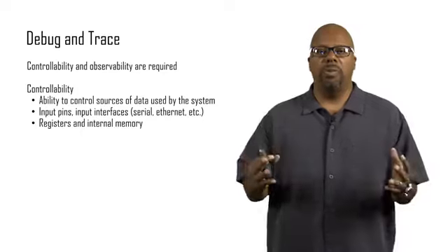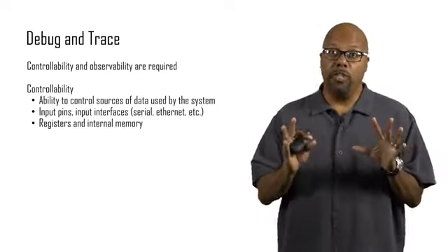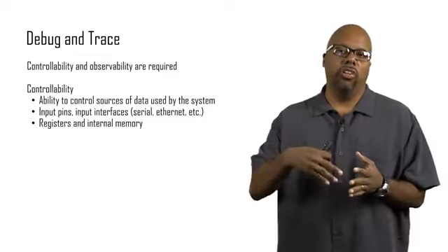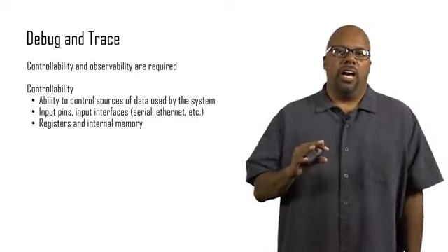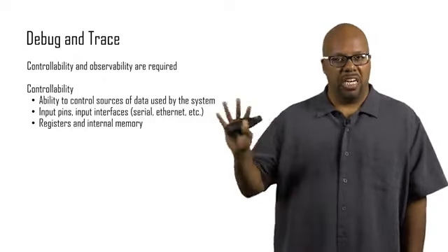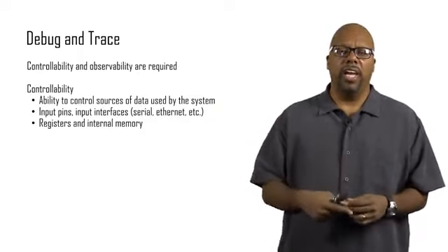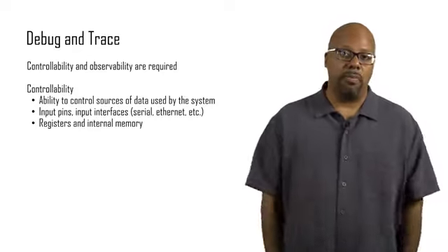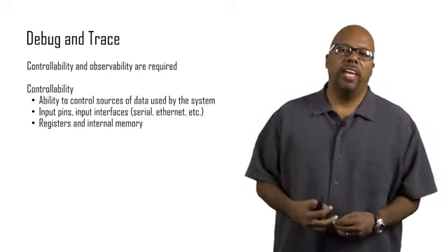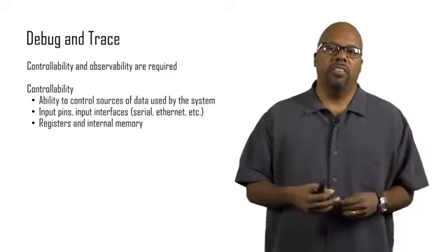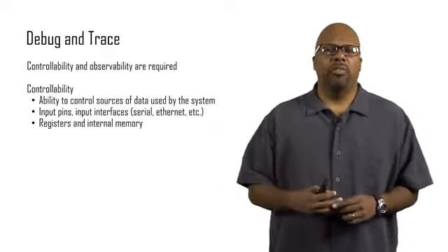Now, the input pins aren't the only thing that you would like to be able to control. In addition to that, you would optimally like to be able to control the internal data, meaning the storage elements, the registers, and the memory inside the chip. We won't be doing that in this class. I'm just saying optimally, if you're doing this professionally, you don't just say, let me control the pins. You go straight into the device and say, okay, I'm going to set this register value equal to 10 and see what happens. I'm going to write some data into this memory location and see what happens. It gives you much more precise control over the behavior of the system because doing it through the input pins can be indirect. But optimally, that's what you would like.